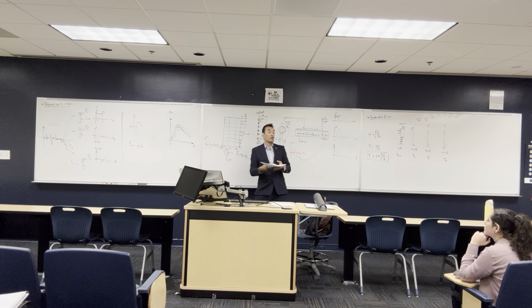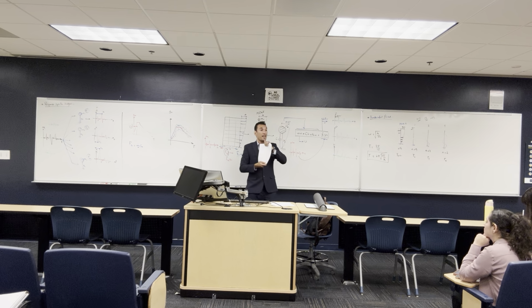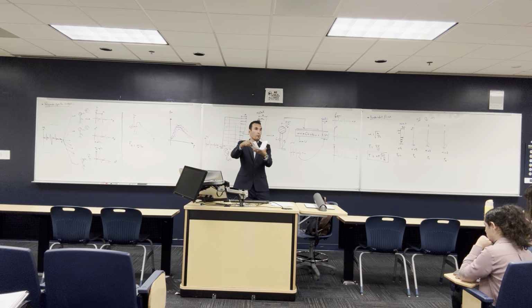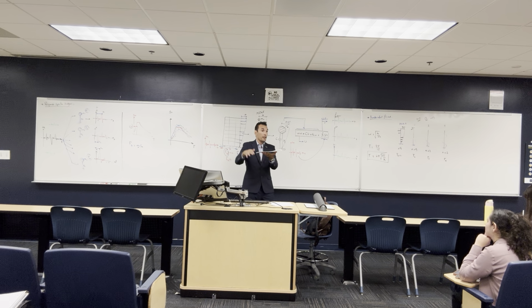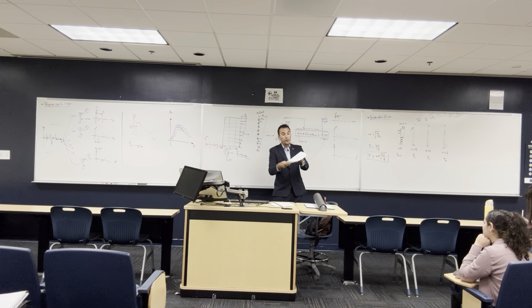The thing is, if my cross section is exposed to compression, I can put concrete. I don't have to put steel because concrete is very, very good in compression. But if it's tension, I can put steel. So if it's tension, it's good. If it's compression, it's good. So I know what I'm gonna use. But with a bending moment, it makes tension down, compression up. So you need steel down, and you need concrete on the top. So that's why we use reinforced concrete, where the bending moment makes tension, we put the steel down.